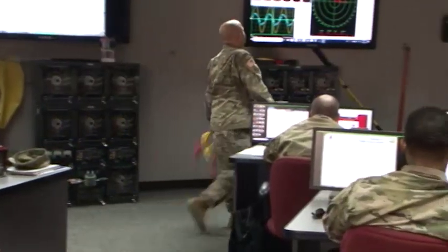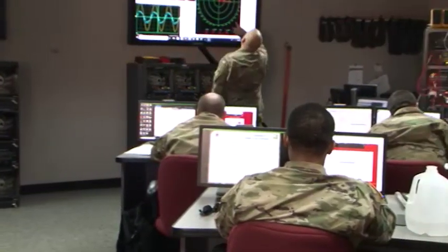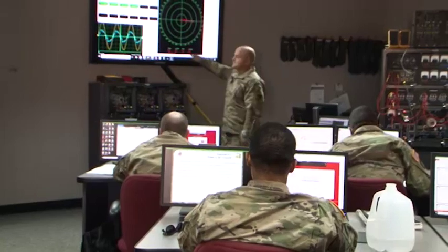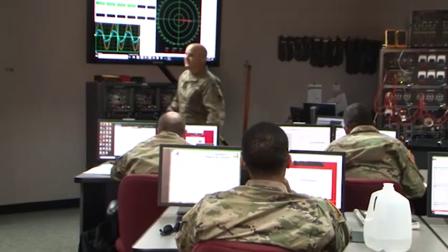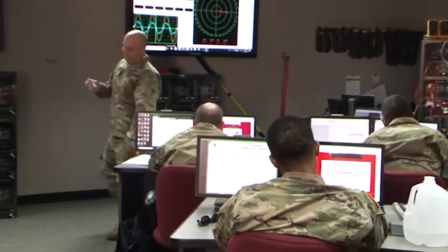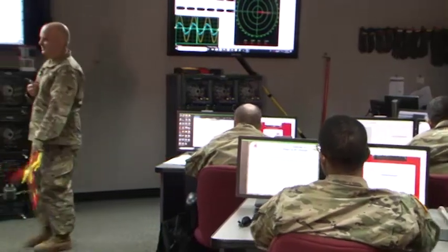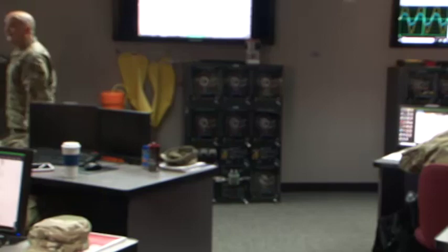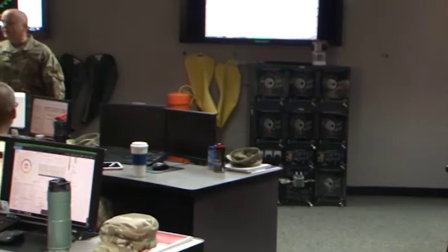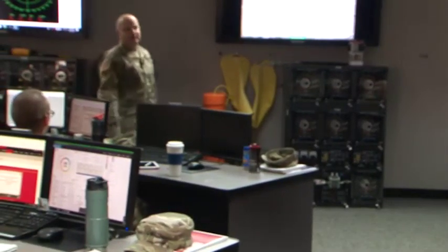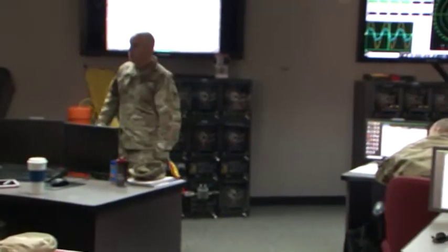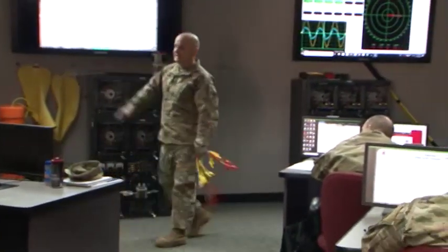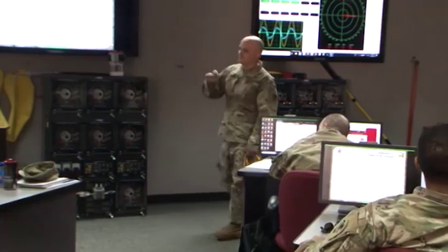In reality, we're seeing this up here. What do we got? 2 degrees there? 2.5 degrees? Yeah. What's the cosine of 2.5? You can put negative 2.5, it's cool. What is it? 0.99999? Yeah. So in reality, your power factor is a 0.99999 power factor right there, which means you do have some slight inefficiency there, but you're almost getting perfect, right? And that's how this power factor plays into this, okay?